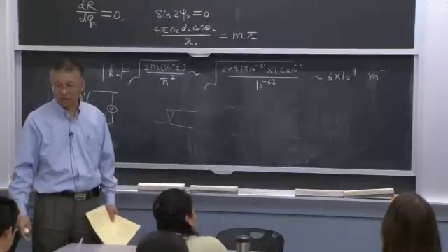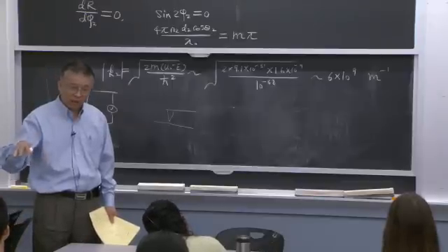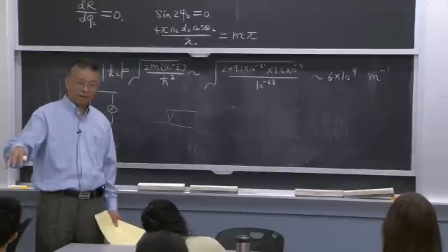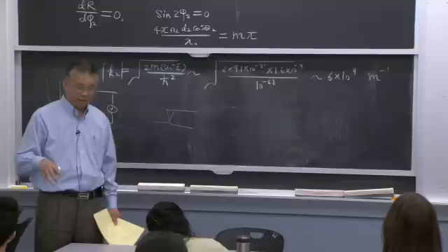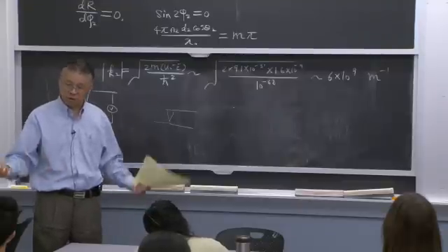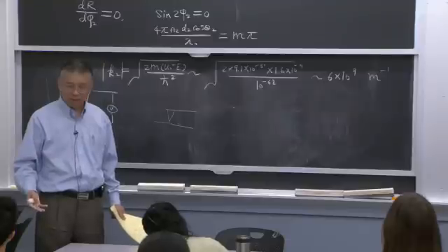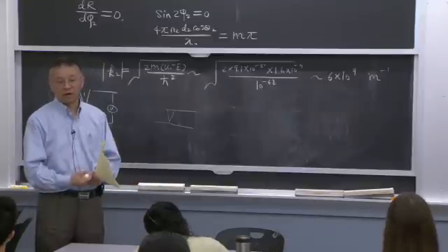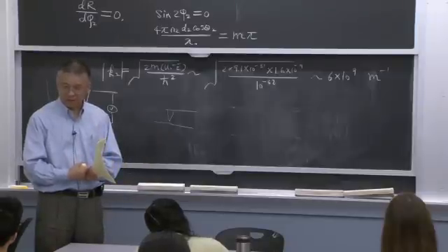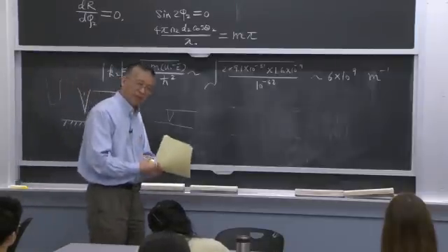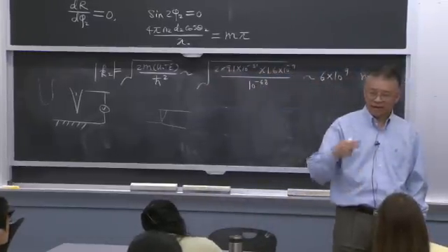If you use a cantilever on the surface, you're worried that you scratch your surface, so how are you going to measure atomic roughness. But he knows, and this is where the basic knowledge comes in, the spring constant. You know the vibration, you know the spring constant between atoms, and you look at what's the spring constant of a cantilever and what's the spring constant between atoms. And the atom spring constant is much stiffer. That means the cantilever will bend, because the stiff one moves less. So people think of this idea because they have the knowledge. You have to apply your knowledge and think about this.